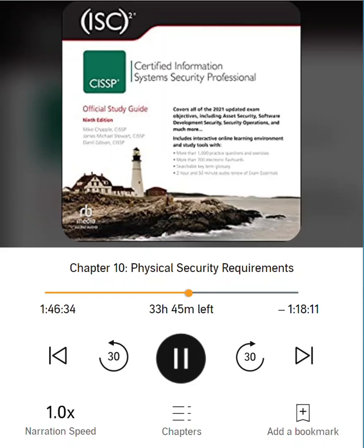Various types of fences are effective against different types of intruders. Fences 3 to 4 feet high deter casual trespassers. Fences 6 to 7 feet high are too hard to climb easily and deter most intruders except determined ones. Fences 8 or more feet high with strands of barbed or razor wire deter even determined intruders. An advanced form of fencing is known as a Perimeter Intrusion Detection and Assessment System, PIDAS.